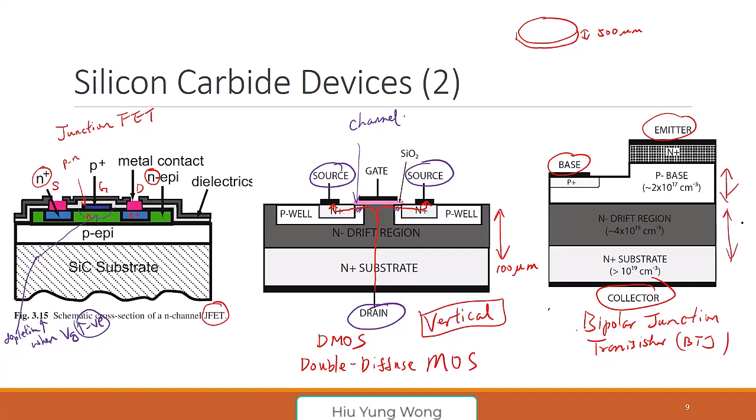This is a vertical BJT to sustain the high electric field. If you have not heard about BJT before, that is fine. It's just like a MOSFET. The base is nothing but the channel, but instead of a gate oxide, you connect to the channel directly. So for this one, if you don't have other defects, your subthreshold slope is 60 millivolt per decade. Remember, we lose some subthreshold slope because of the potential divider effect. But you cannot get that here because it has its own non-ideality. Any questions?